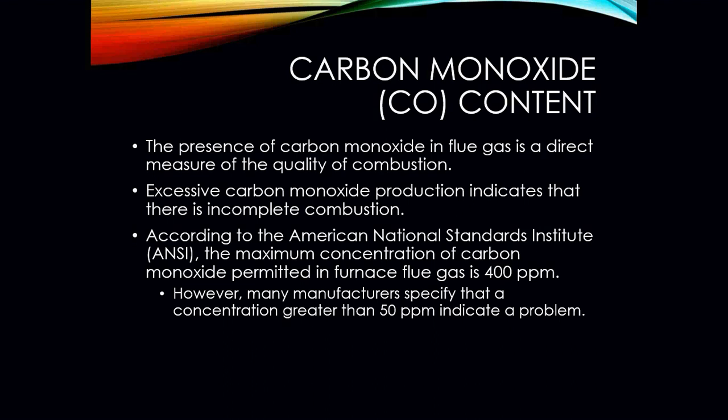However, many manufacturers specify that a concentration greater than 50 parts per million will indicate a problem. When it comes to carbon monoxide, you're going to have some no matter what. We want to keep that carbon monoxide content as low as possible.